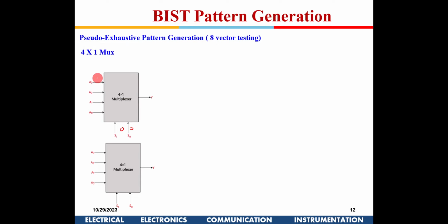So for 0 0, this 0 will be routed. For 0 1, again for 0 0, either a 0 can be transmitted or a 1 can be transmitted. Similarly, for 0 1, from here a 0 can be transmitted and a 1 can be transmitted. If you just blindly tell the ATPG to do it, it will generate 1 2 3 4 5 6, so 2 to the power of 6 test combinations. Similarly here also. Now for these two together, we can have just 8 test vectors, which will more or less tell us that this would function without any fault.